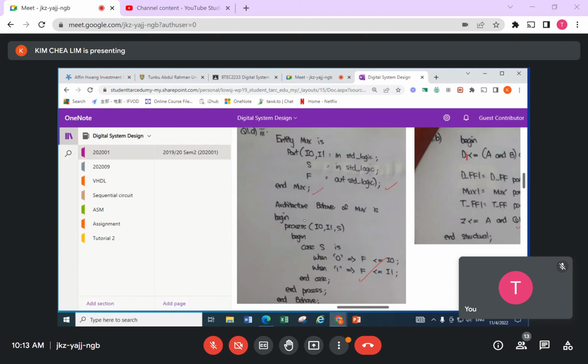For a combinational circuit, all the inputs here go into the sensitivity list, because there is no control input like a clock to make it work. So if any of these inputs change, this program will be called up to execute once.